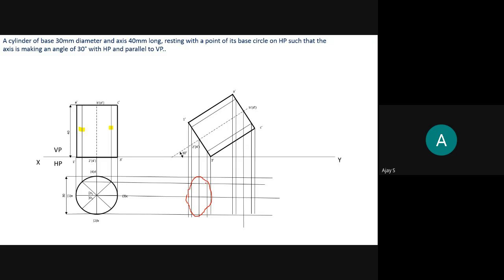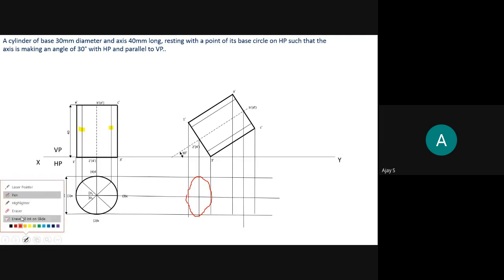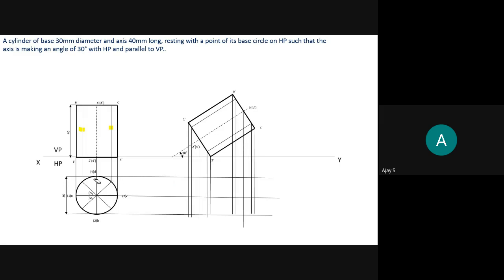To avoid this mistake, we can take another division of those lines. So what I do is, from this point I drop again a projector. From this point, I drop a projector. From this line, I draw a vertical projector. From this point, I draw a horizontal projector, sorry.